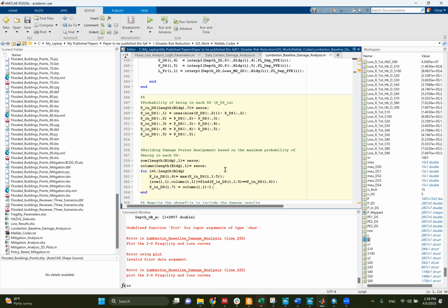However, when we say a building is damage state 1, we are excluding all the uncertainties that we have. Because right now we are making a deterministic decision about the building, right? We're saying this building is deterministically damage state 1. How did you know? Could be damage state 2. So why did we do this?